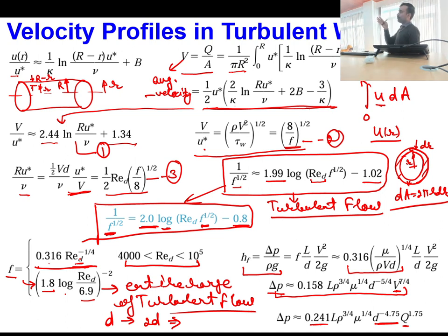But for laminar flow conditions, we already saw in the previous lecture that even if we have pipe roughness, because of the layer-wise smooth flow of the fluid, the roughness does not cause any effect on the pressure drop characteristics. On the contrary, in turbulent flow, because of the fluctuating components of the flow, or fluctuating motion of the fluid particles, the roughness of the pipe surface has a significant effect on the pressure drop characteristics.